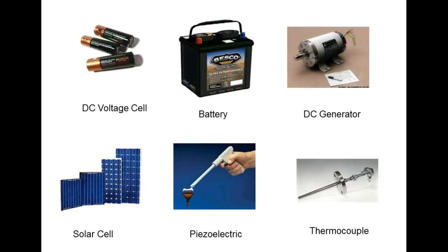And that's what they're doing in your car. In a car, you have what they call an alternator. What type of current do you think an alternator creates? AC. If you put AC on your radio, it'd blow it up. So what do they do? They electronically convert the AC to DC, and it's usually inside the alternator. They call it a rectifier.